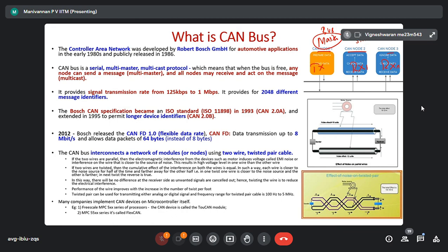Now, once the data is transmitted by, for example, this is my ABS. You applied the brake pedal, correct? Immediately it sends data to engine management, this is EMS: reduce fuel. That means they have to decelerate. So it sends a command to this fellow requesting. At that time this is master, these are slaves.